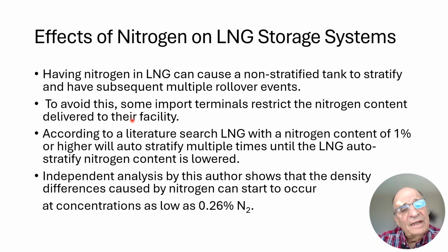To avoid having rollovers, some terminals, import terminals, will restrict the nitrogen content delivered to their facility. Now, typically, the literature shows that 1% nitrogen in LNG will cause auto-stratification.